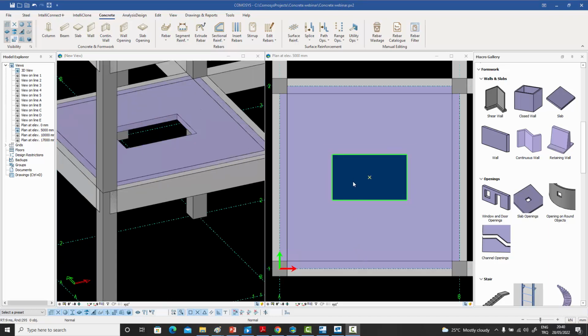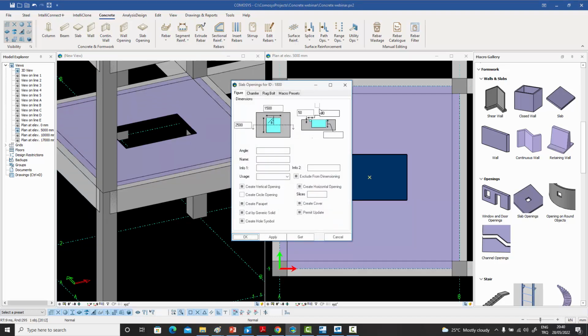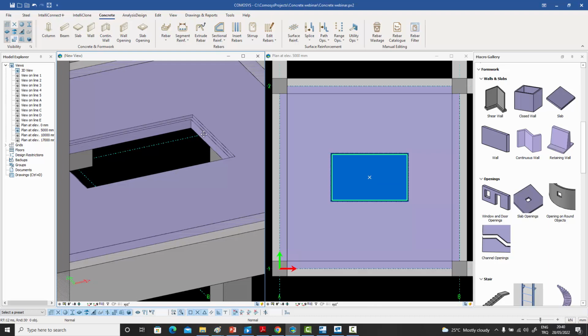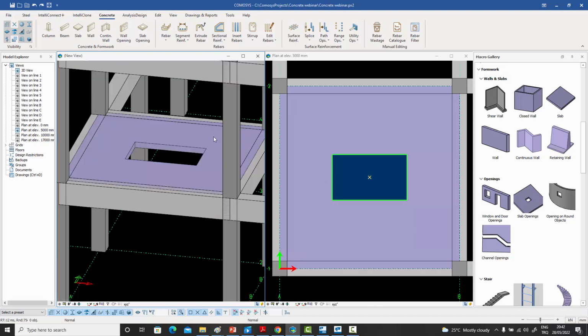Now, instead of creating the parapet, which we just did, we can directly create this little depression on that hole as well. If I were to enter that, we can see that instead of the parapet, I've directly created this depression so that a cover can come directly on top of this hole. And this simple hole command doesn't even end there.